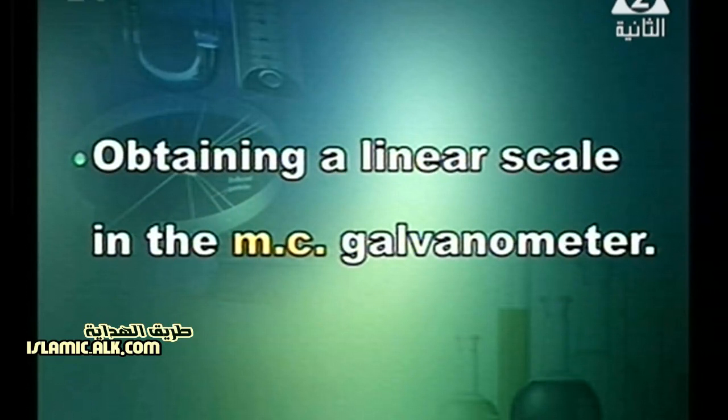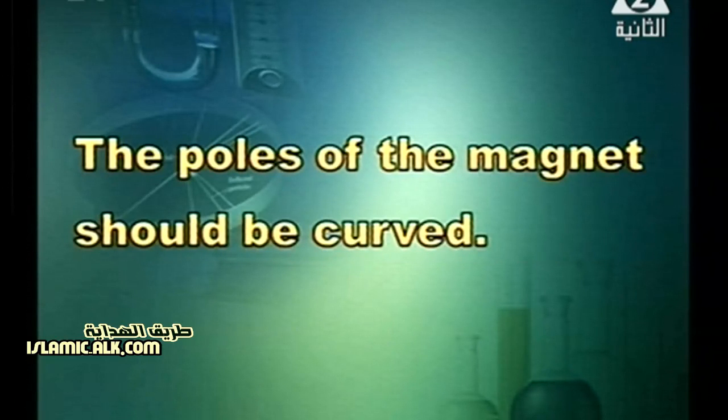What are the conditions required for obtaining a linear scale in the moving coil galvanometer? What does linear scale mean? It means a uniform scale, an equally spaced, equally divided scale. First of all, the poles of the permanent magnet used should be curved.